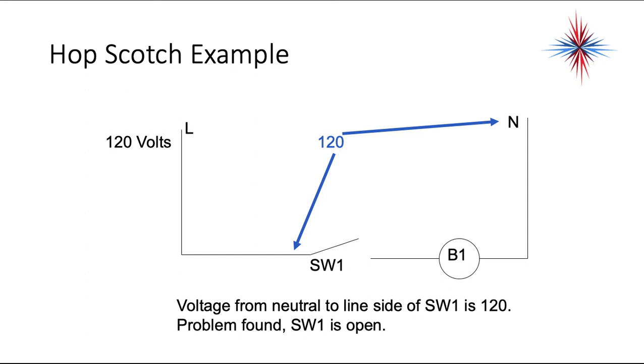So you use your meter. You're going to use voltage most often. Things to remember, very important things: if you're using your meter in resistance to check the ohm readings, you cannot have any power on the circuit whatsoever.